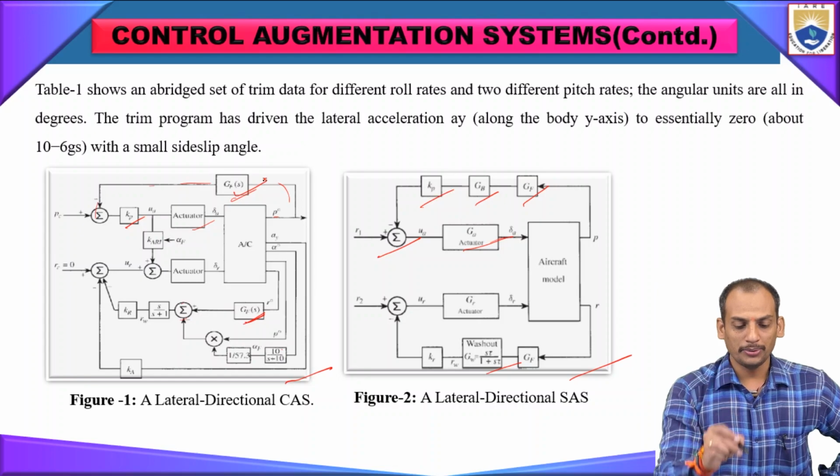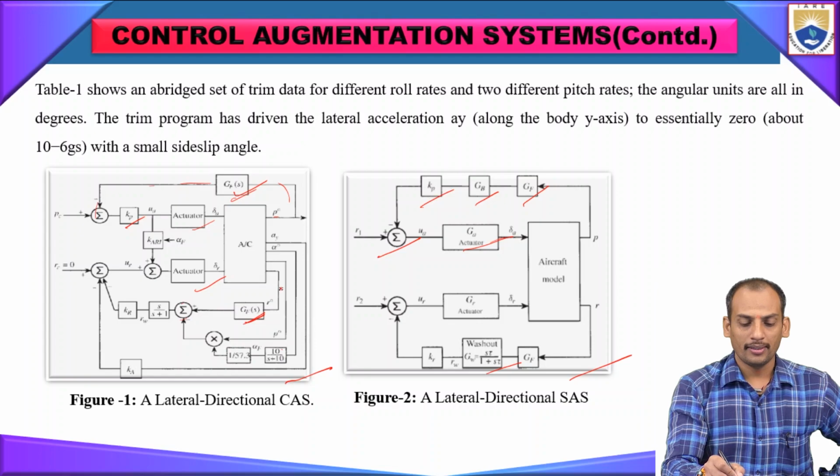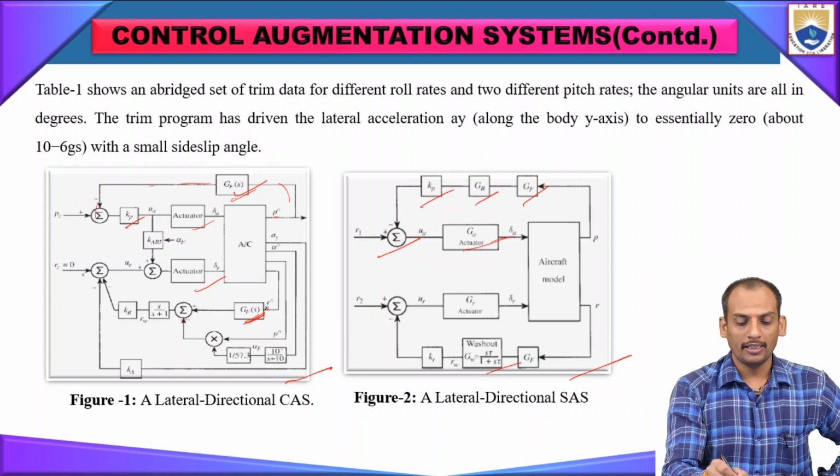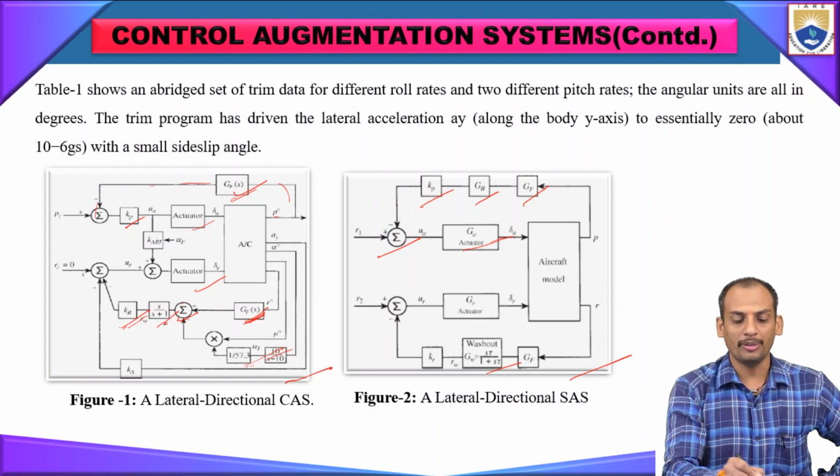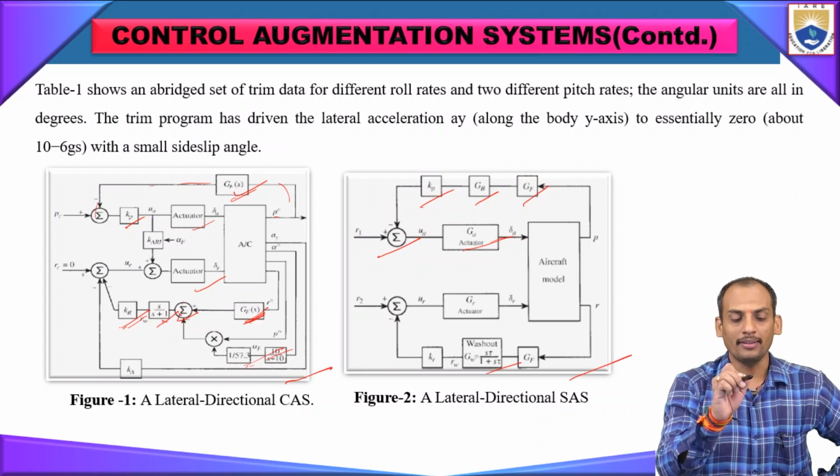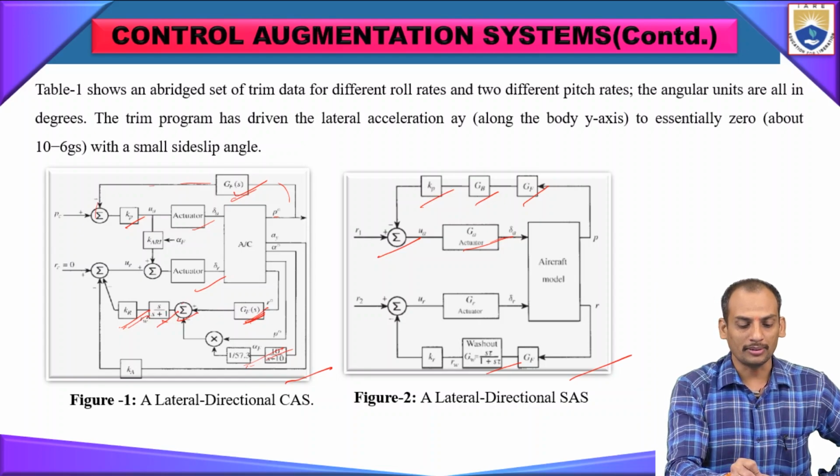As usual, for the actuator installed for the rudder also, the rudder has been looped by this gain feedback and an internal transfer filter gain feedback, which is given to this summing amplifier. Before that, the roll rate moment and a separate transfer function for the roll rate moment are also given here, and from there the actual moment is given to the summing amplifier.